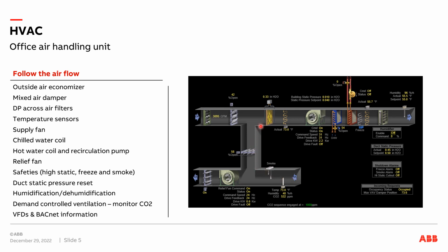Now, I'll swap it around. On my more typical day in Wisconsin, it's a little bit cooler. So what I can actually do is use my outside air for cooling, and then I have very little return air coming in here. If it's 40 degrees outside, believe it or not, my building a lot of times is still in a cooling mode, even when it's chilly outside. So I can take that 40, 50, 60 degree outside air and bring a lot of that into my building for cooling. So that's why you have these mixed air dampers right here. It makes you decide how much outside air do I want to use versus return air.